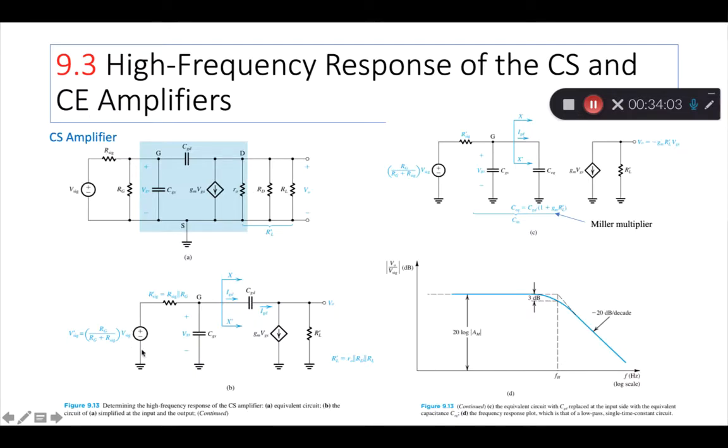So you have one voltage in series with one resistance, so that's a Thevenin equivalent up to this point, right, before the blue stuff. So the values of the Thevenin source, the voltage source is this, and the Thevenin resistance is this R signal prime, which is R signal in parallel with Rg. Then the first capacitance and the second capacitance are still there, and your dependent source is still here.